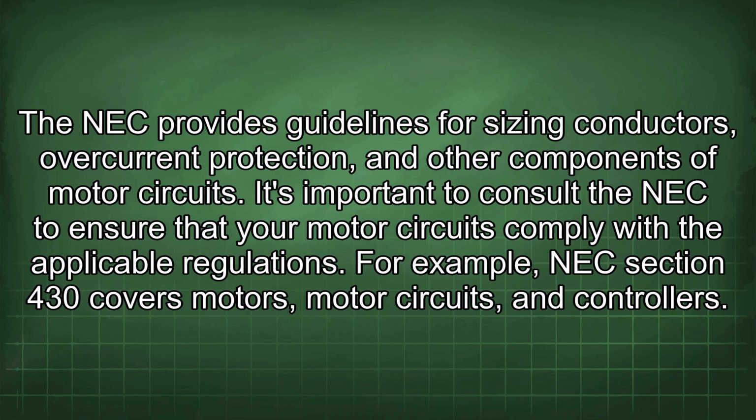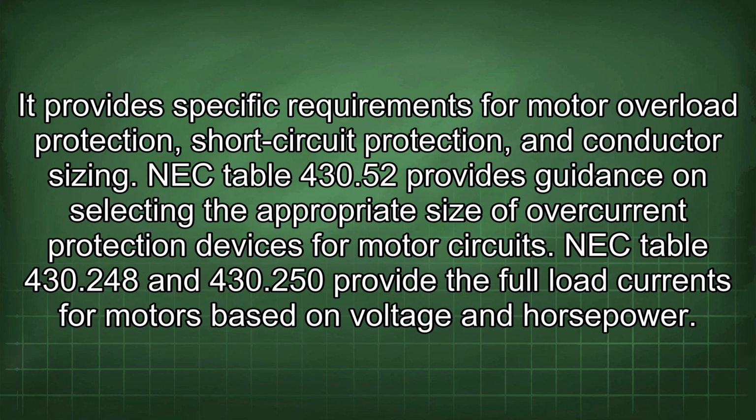For example, NEC Section 430 covers motors, motor circuits, and controllers. It provides specific requirements for motor overload protection, short circuit protection, and conductor sizing. NEC Table 430.52 provides guidance on selecting the appropriate size of overcurrent protection devices for motor circuits.